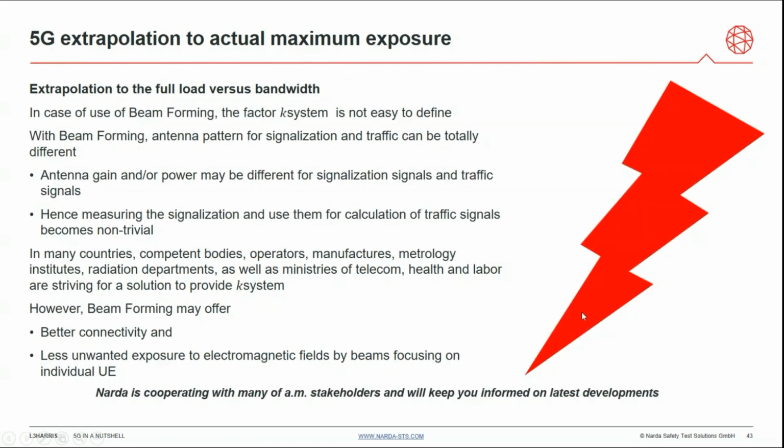So the extrapolation to maximum exposure is not trivial, because this beam forming factor is not so easy to define, and the vendors need to define that depending on their system or the system architecture. The beamforming antenna pattern for signalization and traffic can be totally different. That is also what we found out with recent tests.